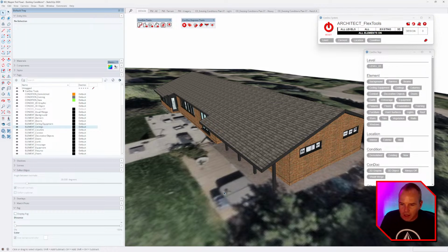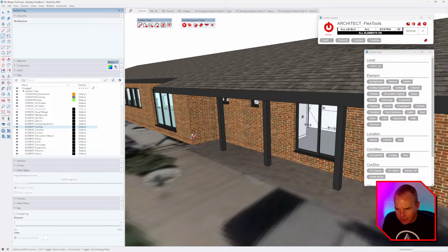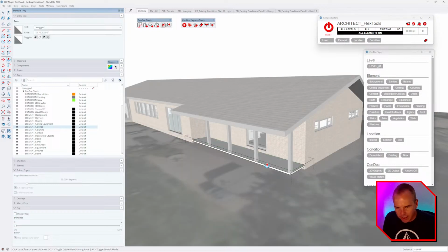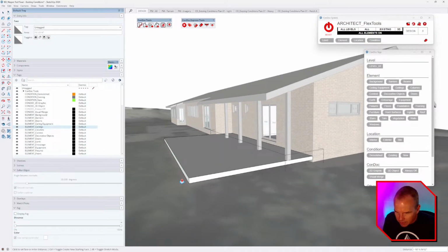All right. So to properly plot that point, I could just draw a rectangle here and then group it and then hop in there. When it's selected, I can just hit enter. I'm just going to make it 6 inches, and this distance right here is 4'1". And as I pull it out, I'm going to call it 10 feet, 11 inches like that. So this way, my dimension from here to here is a clean 15 feet.